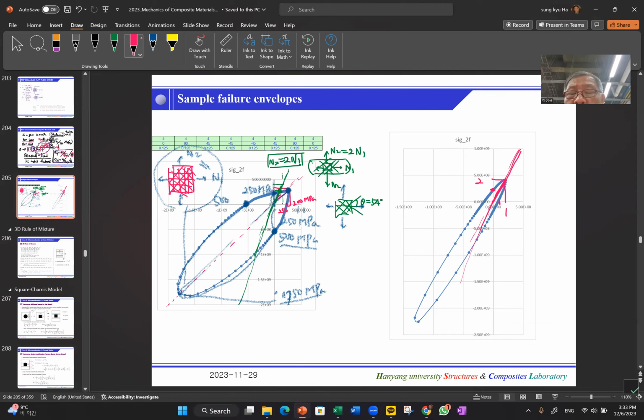See this plot, we chose the biaxial 54-degree, and this angle is well known to give us the best for the pressure vessel. The pressure vessel is again the 1:2 ratio. So as you can see, biaxial 54. 54 again is the plus minus 54 symmetric.